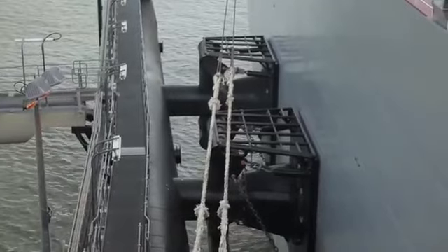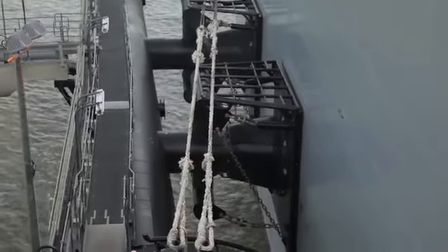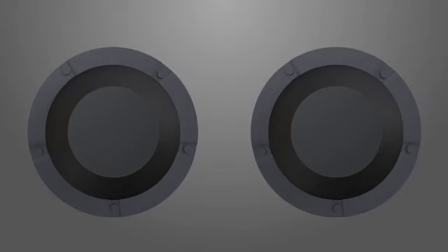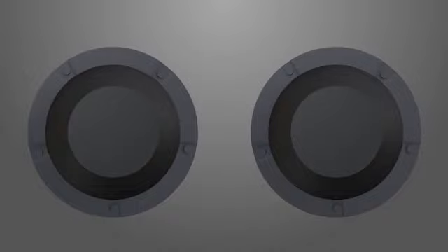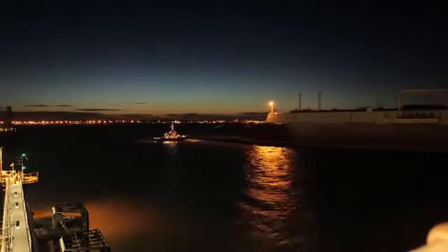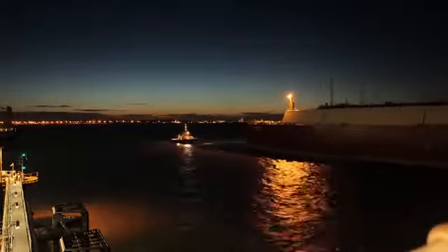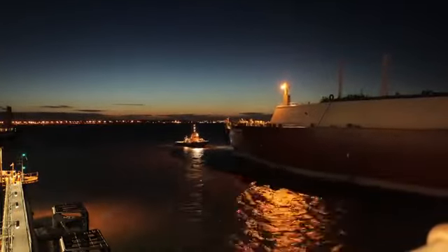Fender performance and life cycle vary dramatically based on the type of rubber used, natural or synthetic, and virgin or recycled, and the compound composition of the rubber. Compound composition has a dramatic impact on velocity factor, temperature factor, and fender life cycle.